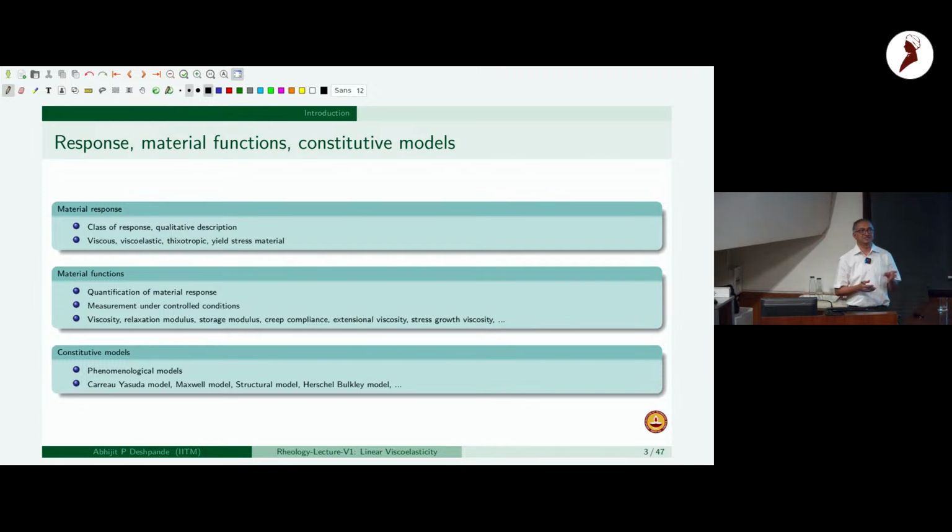I can say it's a nonlinear viscous fluid, but nonetheless a viscous fluid, so that there is no change in geometry, no change with time. So when I am interested in kilometers of pipeline transport, crude oil, which is actually a viscoelastic fluid, we consider largely a Newtonian or at most a nonlinear viscous fluid.